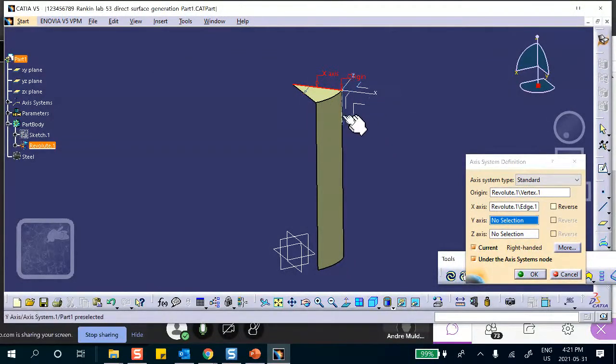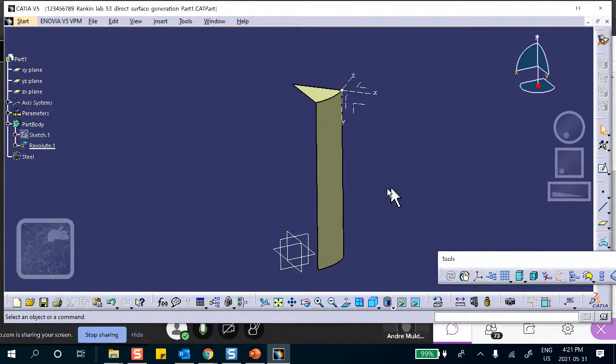If I use this coordinate system, these two edges lie in the XY plane of that coordinate system. If I had done it differently, it would have been different. But the way I did it, these two edges, back edges, lie in the XY plane. No displacement in Z, rotations opposite of that coordinate system. Okay? So let's go ahead. We created that because we're going to need it in a few minutes.